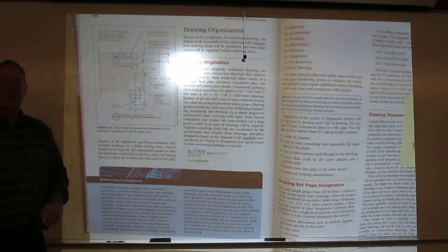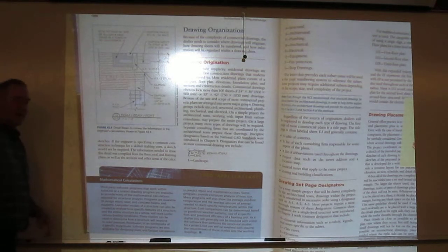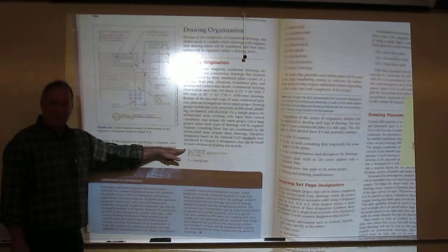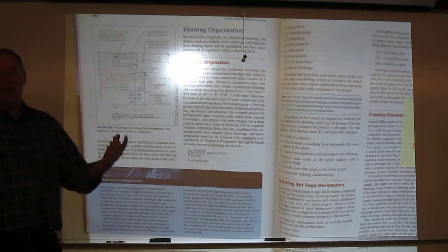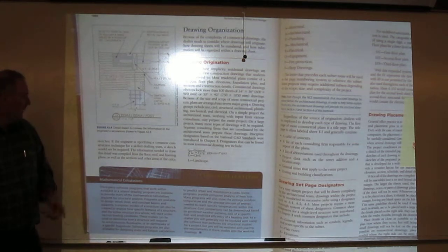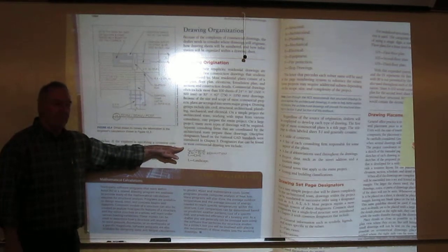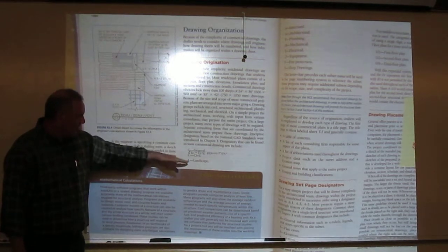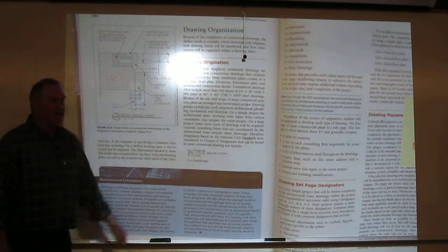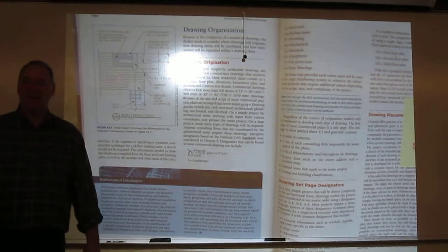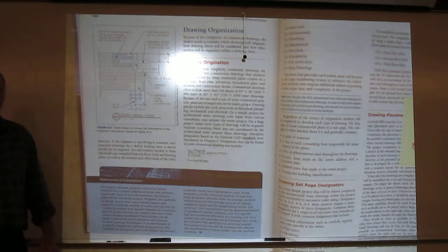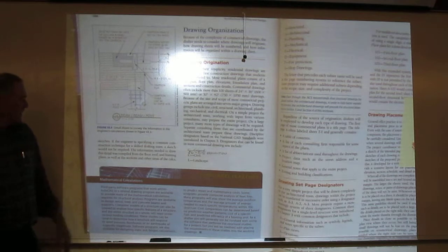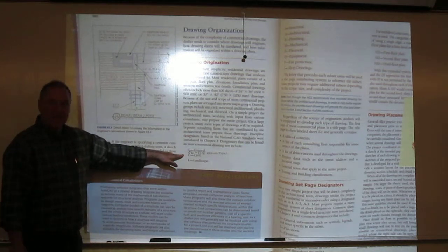Any commercial project will follow this scenario, where you'll start generally with a G sheet, which is general. This would have all of your subs on it, it would have a location map, these types of things that are giving you information. And they will have a G in front of the name. After that, I wrote it in here, it's not done, there might be an SD. That is for site demolition, in case we have to tear a building down, maybe cut a few trees down, remove them, whatever the case might be.